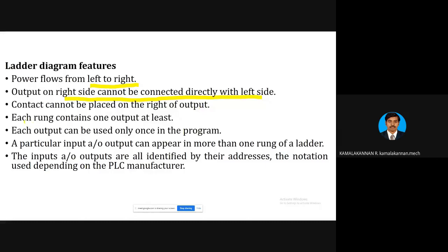Then, each rung contains at least one output. Rung, as I have told you, means a horizontal line. So each horizontal line will have at least one output. Next one is: each output can be used only once in the program. So one output can be utilized only once in the program.